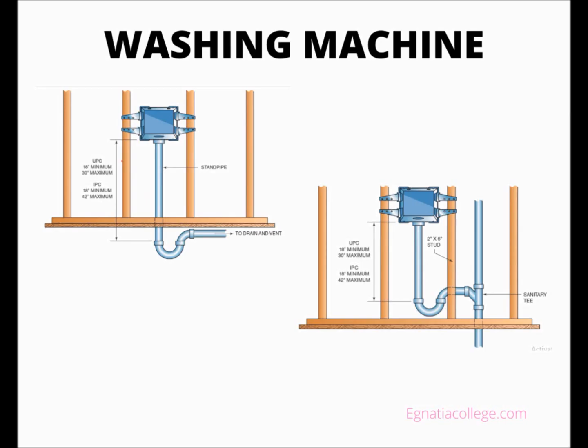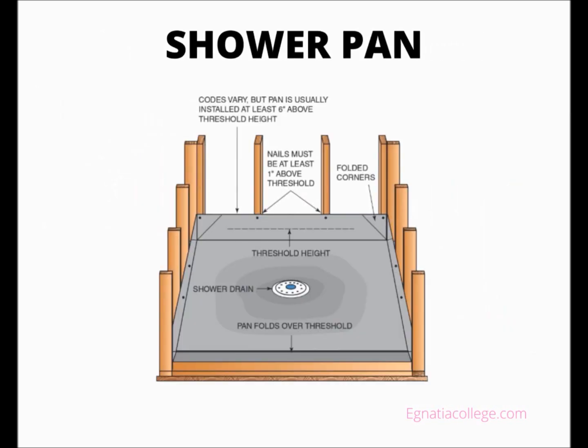The safety pan drain is typically 1-inch copper or plastic pipe made of water distribution materials. It does not have to comply with drainage fitting regulations. The drain typically terminates on the exterior of the house and cannot directly be connected to the drainage or vent system. Check your local codes for termination locations and heights of the washing machine safety pan drains above the ground.